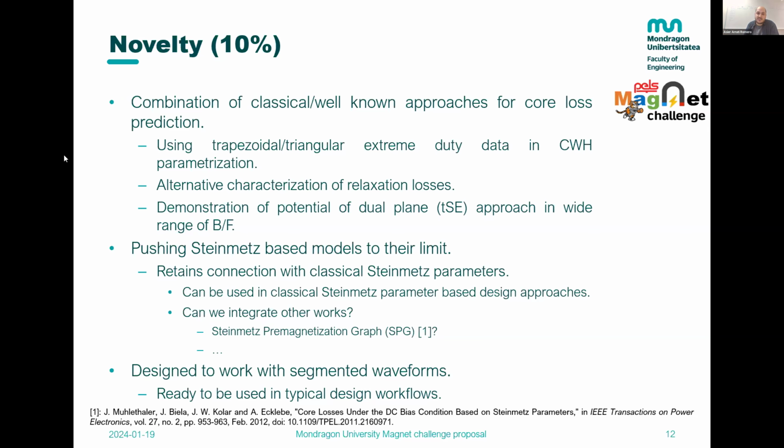We have proposed an alternative way to characterize the relaxation losses. It should be less accurate than the one proposed before, but for us, I think it's an accurate enough approach. And we have also demonstrated that just using the 2 planes, hysteresis and eddy losses, that the estimates proposed over 100 years ago, we can actually get very good results in a very wide range of flux and frequency. We have shown that you can push the estimates-based models quite a lot further. You can improve the precision a lot while retaining the connection with the classical estimates parameters.